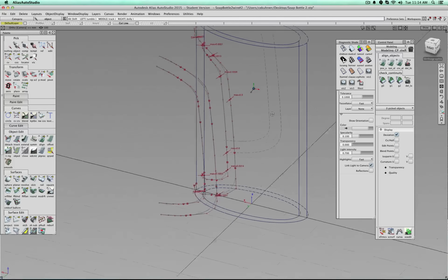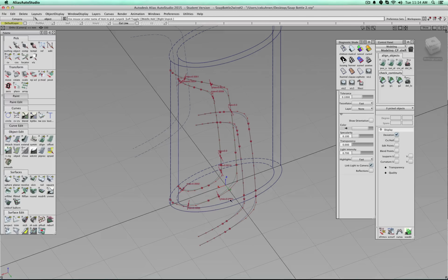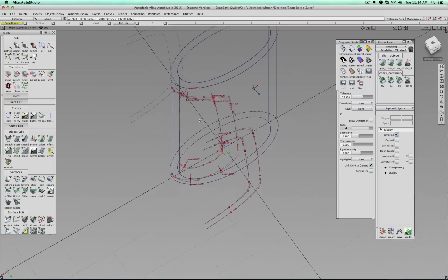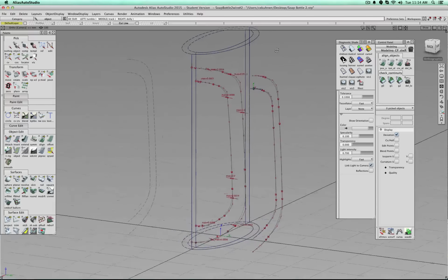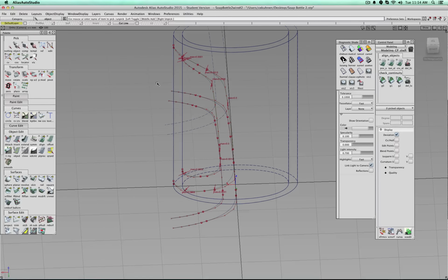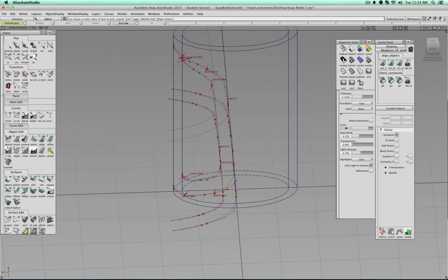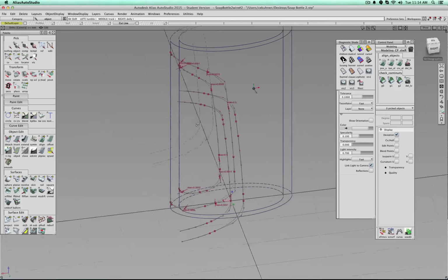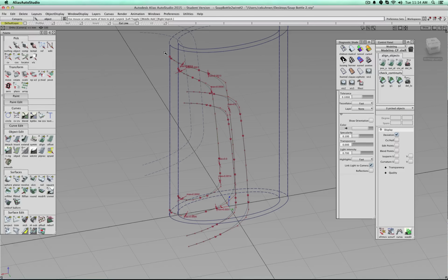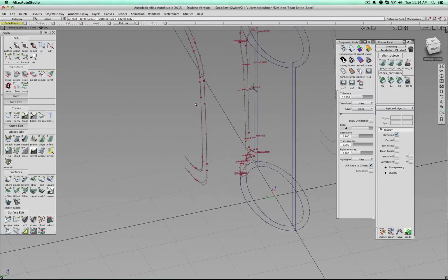So here I'm back, and you see I have generally pretty good matches. Okay, so the whole idea is that those are really nice and simple curves. The amount of endpoints is very, very small, and when you project a curve onto a surface, so it really is on it, you have a ton of spans. You don't want that.